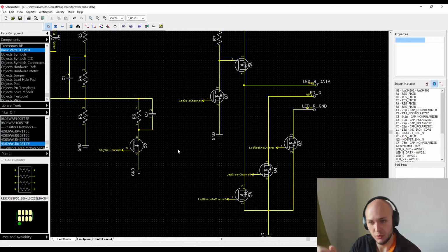But the problem is they have a certain capacitance, and it's nicer for the ICs to have a resistor for them, because then the internal drive MOSFETs in the IC, in the controller, aren't that pushed. So we will most probably, certainly, add resistors later.